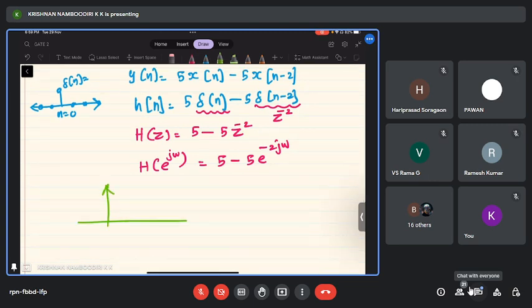A low pass signal will have a frequency response like this, right? So in the discrete domain, we need to consider the frequency components between minus pi and pi, correct? So the discrete frequency will be between minus pi and pi. That's a periodic signal actually. So the same shape will be repeated like this, because I have told earlier, right? When you are sampling a signal, the frequency spectra will repeat, right? So here, this is between minus pi and pi, the discrete frequencies.